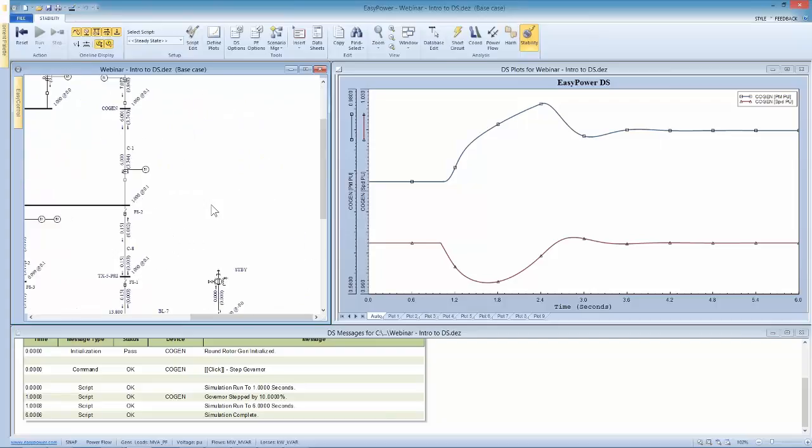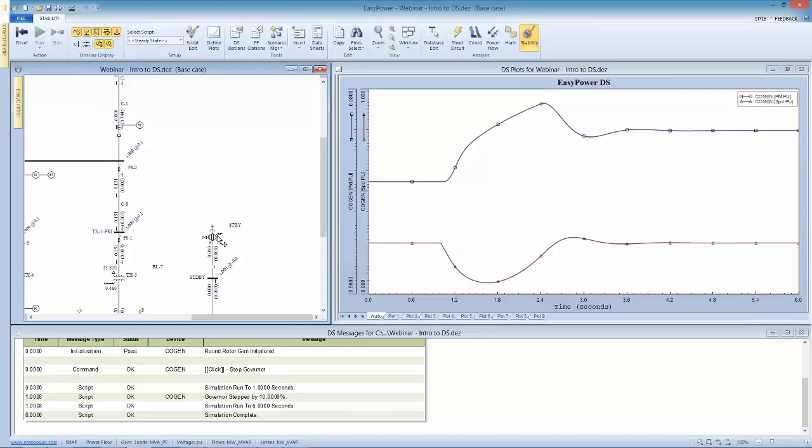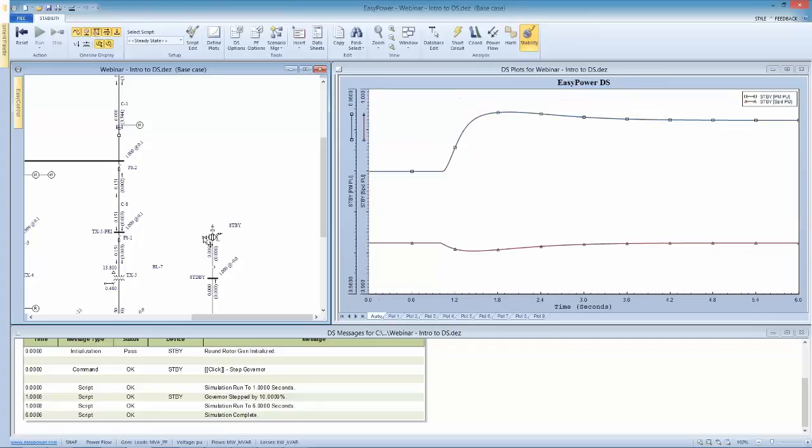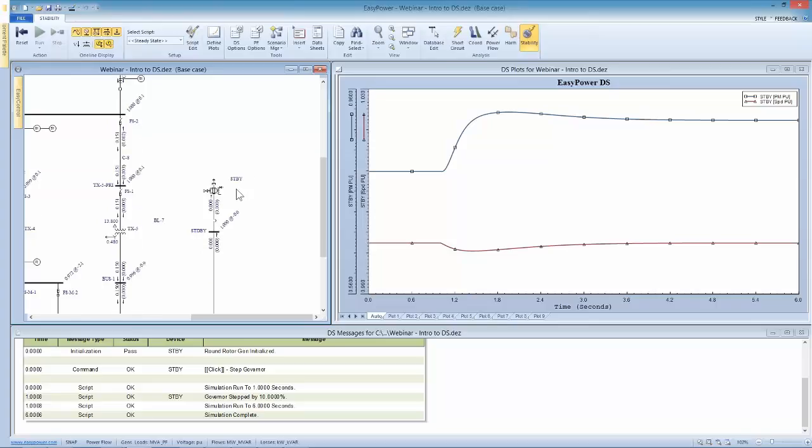If we go down to our other system generator, we can perform the same. All I'm doing is double clicking on the icon in that particular element. Again, the excitation system for emergency standby is much snappier and has less overshoot and a quicker response. And likewise, the response to the load step test on the regulator. Okay, so that's again built into the double click function of the tool itself.